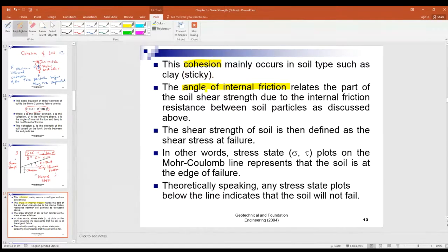Sticky rice, right? Very sticky particles. But sometimes under a heavy rainstorm, the cohesion could be lost. In other words, the soil could suddenly lose all its cohesion. So the whole soil mass could be sliding down, just like an unstable slope. Under very heavy rainstorms, many slopes are prone to fail, just because they are losing the cohesion. So the shear strength has lost some part of it.